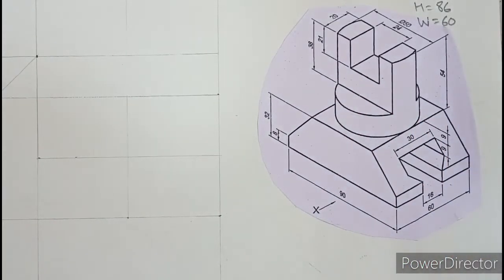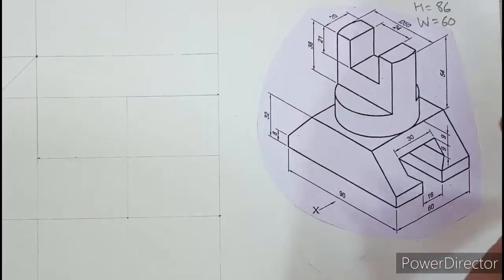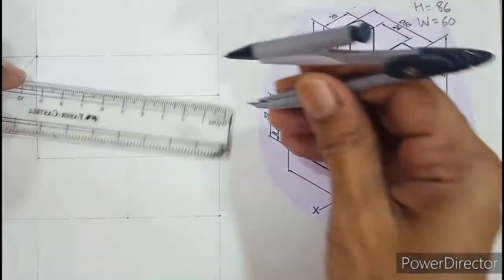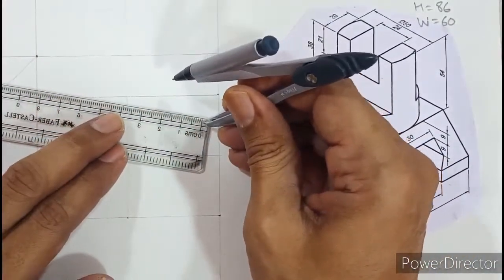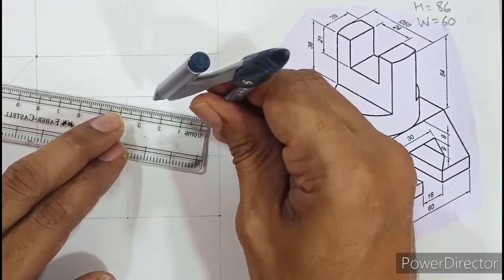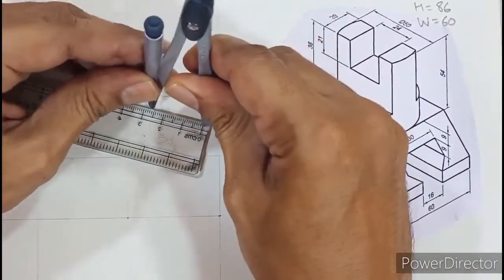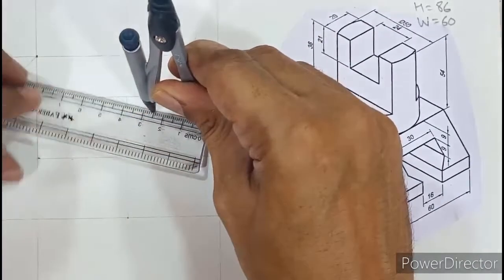So now let us draw a circle of radius 25, diameter 50. Here I have the compass, I will set 25 millimeters. I always reverse the scale like this, because on the rear side the compass needle rests properly on the calibrations. So I will set 25 millimeters in the compass. That's what I've done.